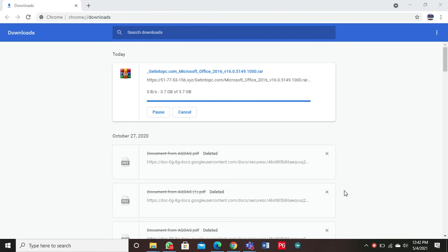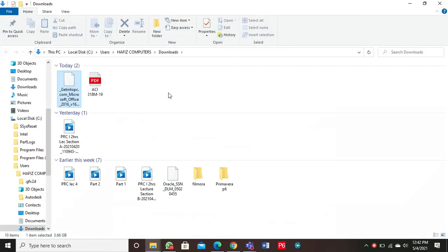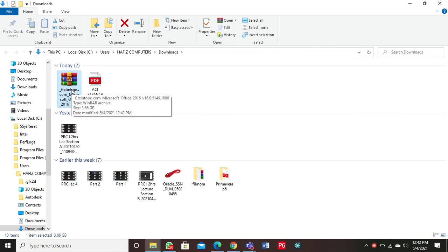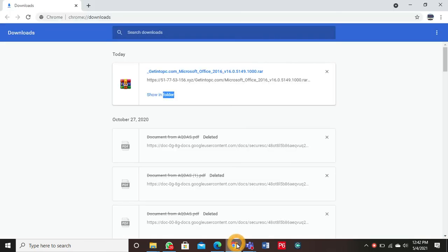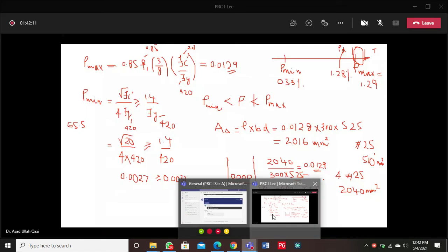And while visiting the site before concreting, if you are doing top supervision as a designer, it is your responsibility to make sure that according to your calculations, covers are provided in the actual beams.